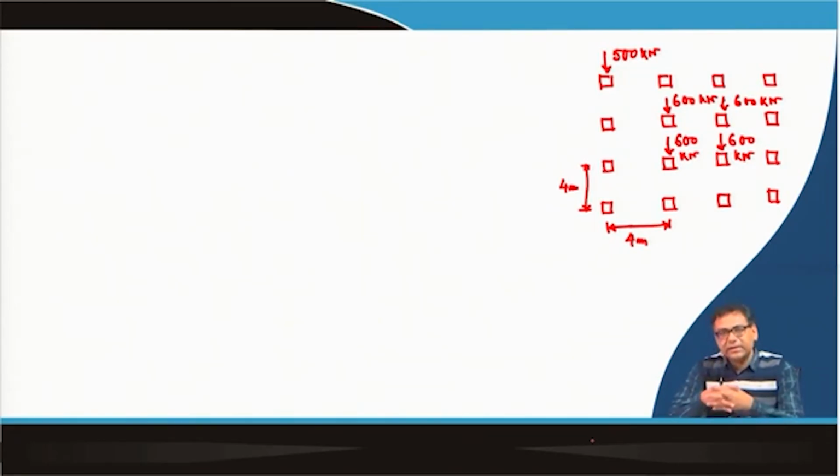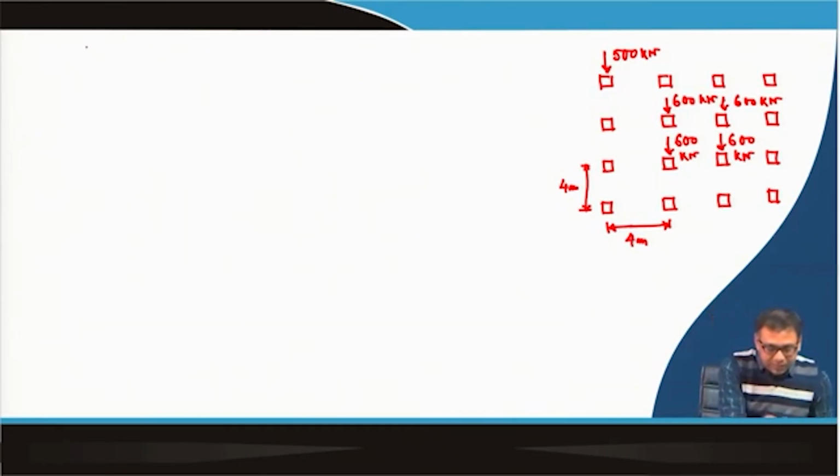But in this case, it is observed that we cannot provide individual or isolated footings for this type of soil and this type of loading condition, because the footings overlap each other or there may be differential settlement issues. So we have to provide a combined foundation for all the columns, that means we will provide a raft foundation. So I will discuss the design of raft on clay.